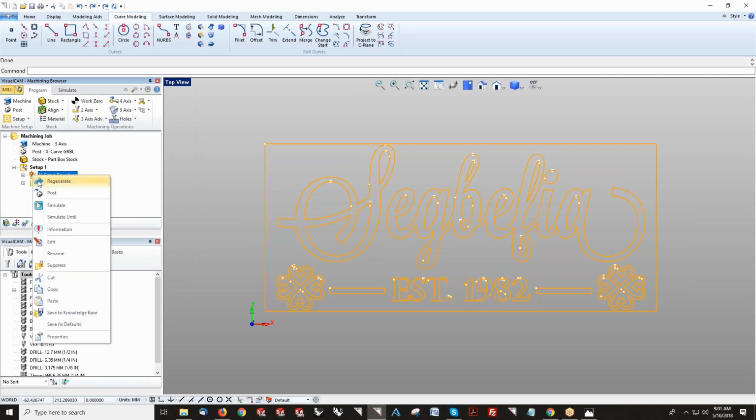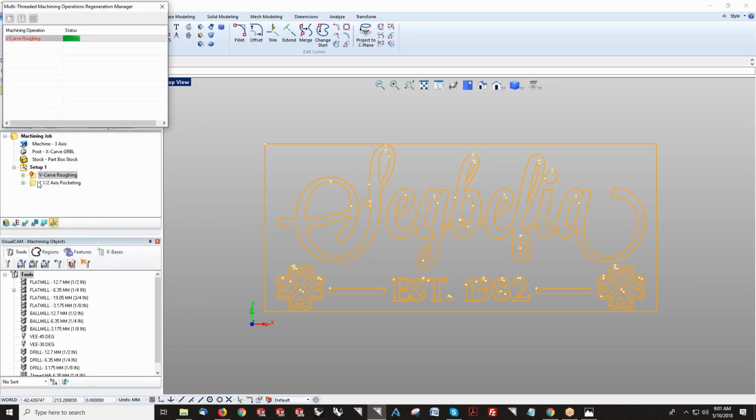So now I'm going to go ahead and generate this toolpath in here, and it's going to compute the toolpath, and it'll automatically create a draft. Basically it'll create like a stepped area, so it accounts for the finishing tool, which means it'll take into account the draft angle that you put in, the taper angle that you put in for the finishing tool. So when the roughing operation computes the offset, it knows that it needs to account for the finishing tool's taper angle automatically. So that's what the V-carve roughing operation does for you.